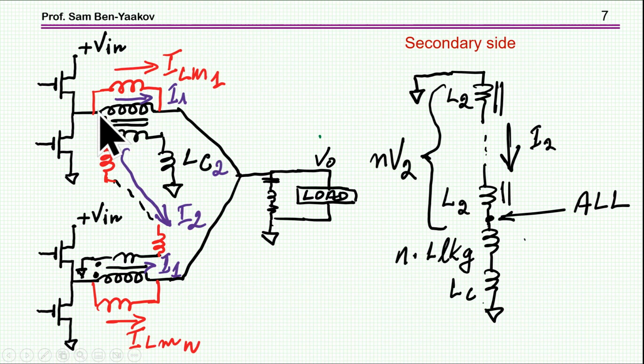So now I have a transformer here, or a coupled inductor. There is a voltage on the primary, which of course is reflected to the secondary, and all these secondaries are now connected in series, and I'm showing here the secondary side. We have the secondaries all connected together, and then I have the leakages N times, whatever number of stages I have, and if I like, I can add another L_C. So this will be this secondary. The primary again is this inductor. This is an ideal transformer. An ideal transformer is defined by having infinite inductances, so they don't add to the current, but it has a perfect coupling between primary and secondary. The original unit is assumed to have a coupling coefficient, which is of course smaller than 1.